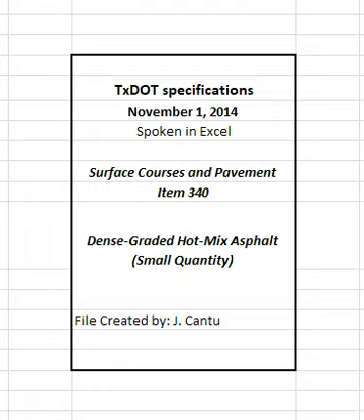Process the RAS by ambient grinding or granulating such that 100% of the particles pass the 3/8 inch sieve when tested in accordance with TEX-200-F, Part I. Perform a sieve analysis on processed RAS material before extraction, or ignition, of the asphalt binder.